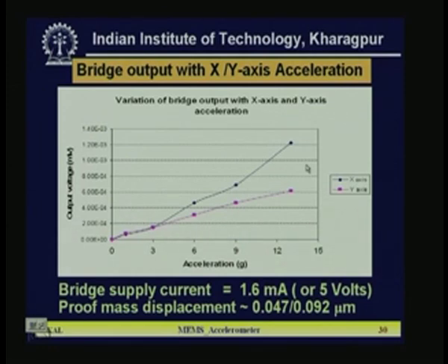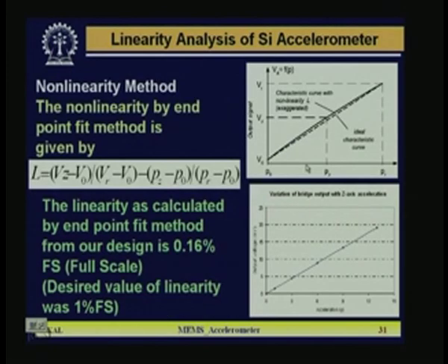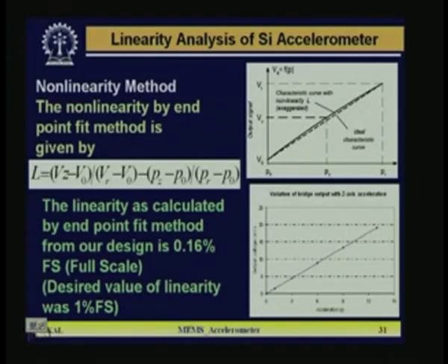Now, at the end of this design, another parameter we discussed here is linearity. Linearity is another point: we want it to be linear, within 1% linearity. The linearity can be calculated from the endpoint fit method. So, here is how we can go about calculating the linearity value.